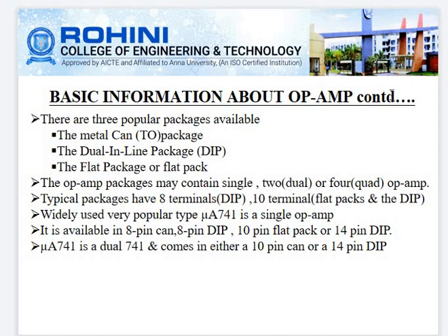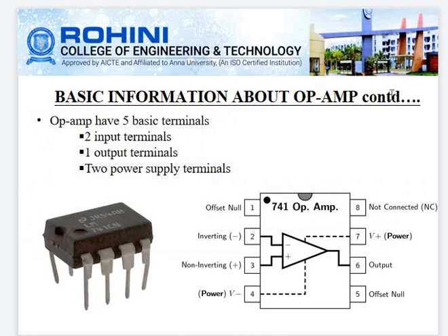The widely used operational amplifier is the μA741. It's a single op-amp. It is available in an 8-pin can, 8-pin DIP, 10-pin flat pack or 14-pin DIP. The μA747 is a dual 741 and comes in either a 10-pin can or a 14-pin dual inline package.